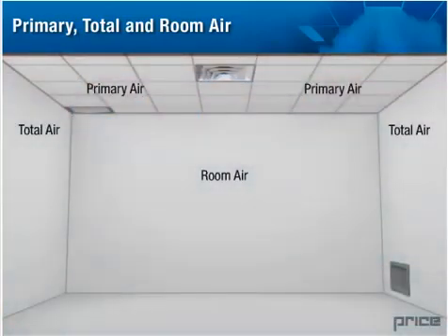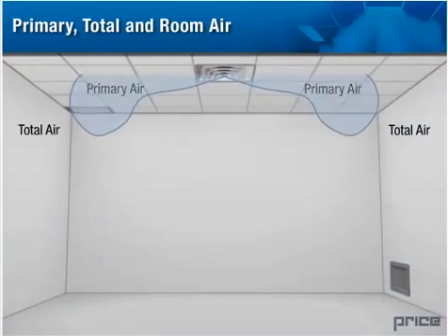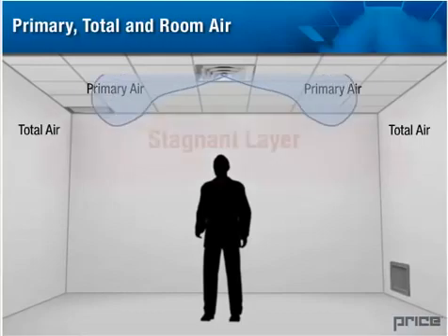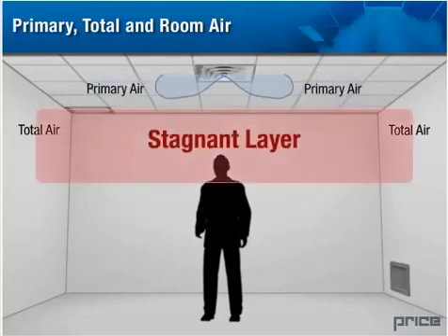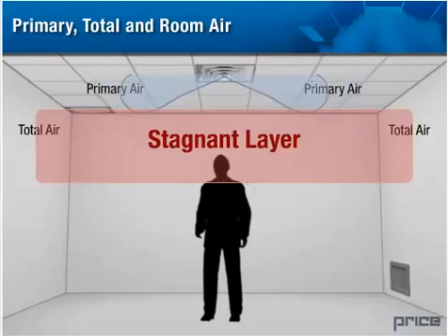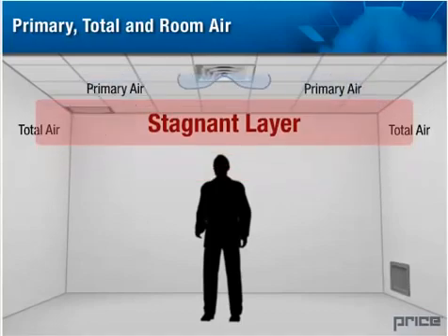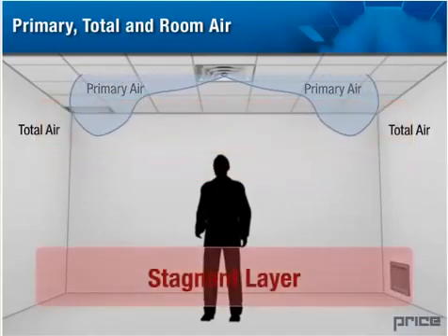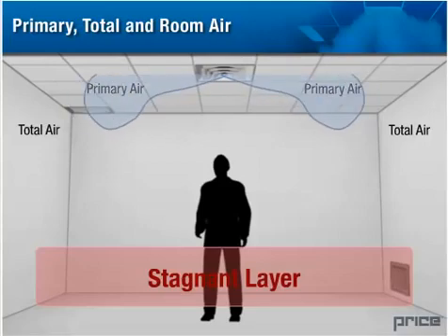When air movement does not occur, usually as a result of insufficient outlet velocities or poor outlet location, a stagnant layer of room air is formed. The formation of this stagnant layer means that the entire volume of air in the room is not being properly conditioned. It is always desirable to keep the stagnation layer above the occupied zone in cooling mode and as near to the floor as possible when heating from above to reduce the chance of occupant discomfort.